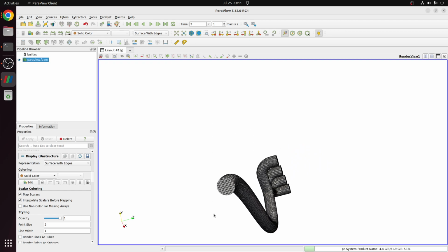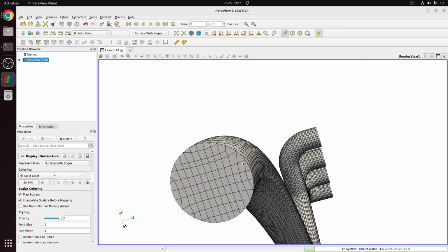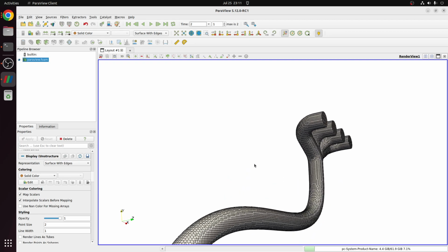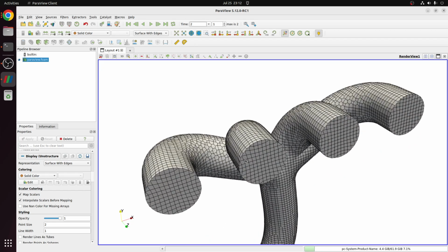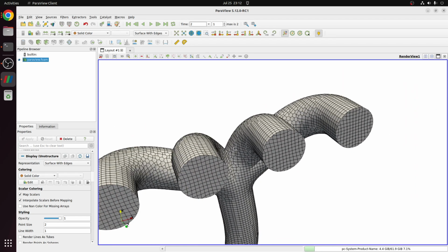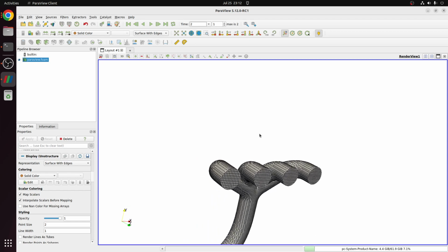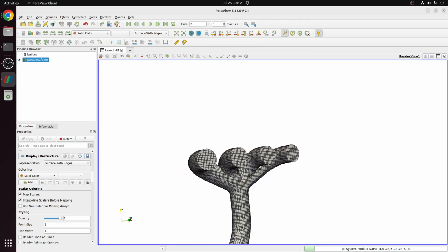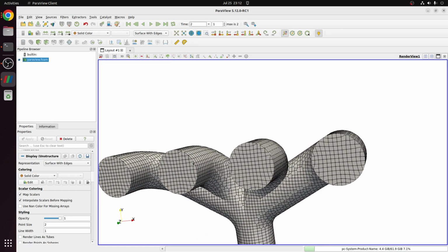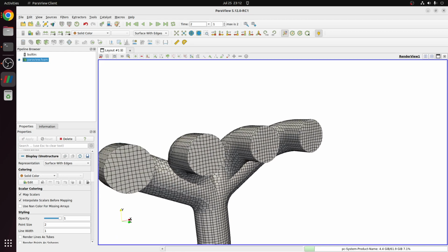For most of the simulation, Converge also works with this type of mesh only. For most simulations, this mesh is good enough, except aerodynamics or very specific cases where you want the heat flux or cavitation captured accurately, then you need the boundary layers. Otherwise, this mesh itself will be decent enough.